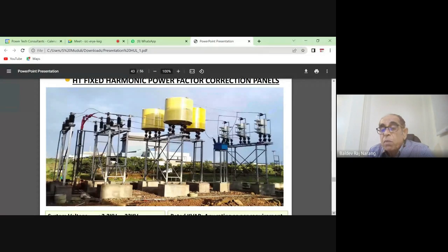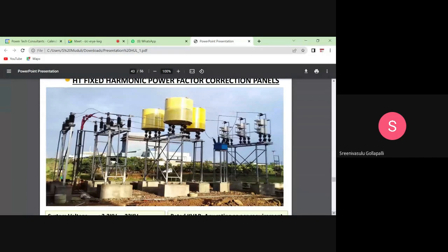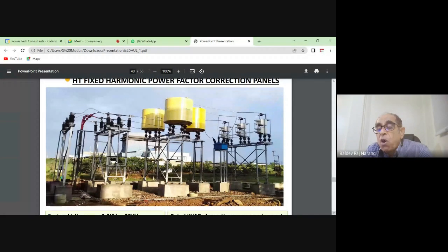With the zigzag winding, the arms of the zigzag transformer act against each other and they cancel out the third harmonic. So the design takes care of the third harmonic, mainly for the third harmonic but not for other harmonics. Other harmonics, we handle with a 14% reactor, or with an active filter, or with a harmonic mitigation transformer.